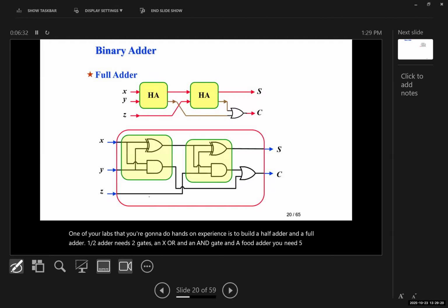Now, we can also build a binary adder subtractor. For this, instead of having the 4 NOT gates, we can have 4 XOR gates. One input of the XOR gate is connected to Y, the second number, and the other input is connected to a control signal or the mode signal M. And that mode signal is also connected to the carry Ci or C0.